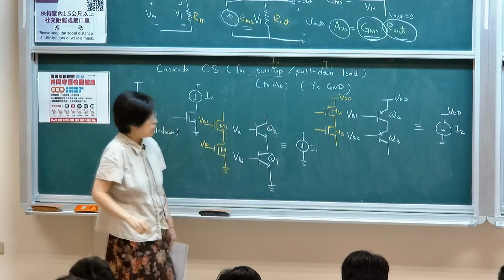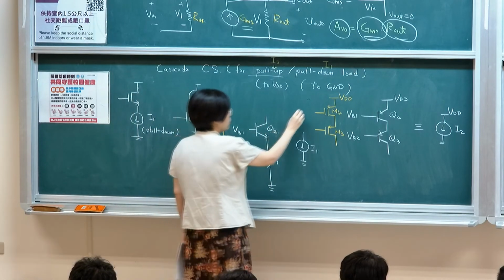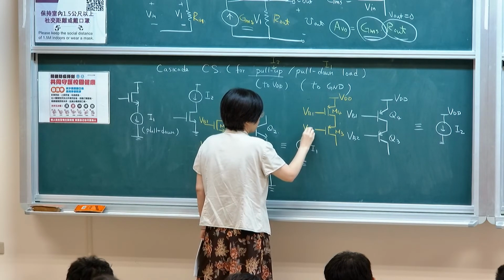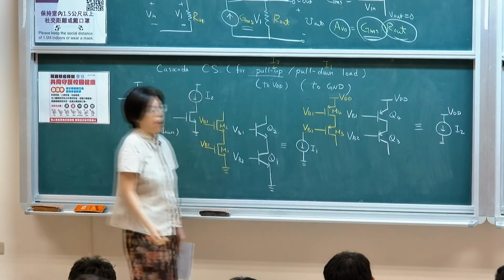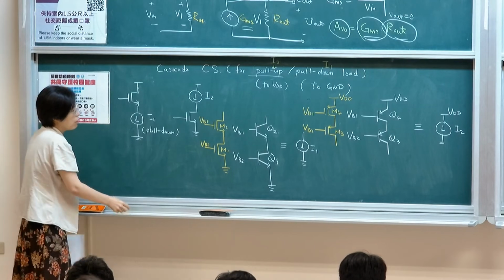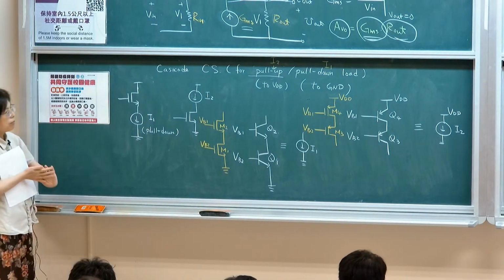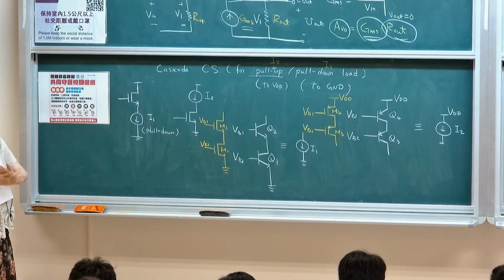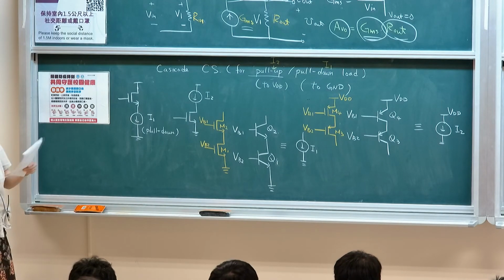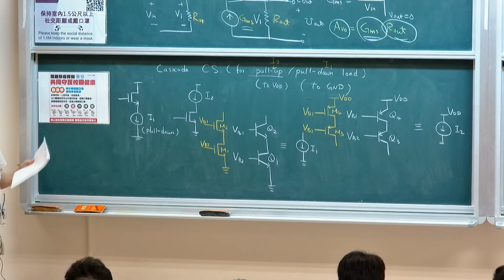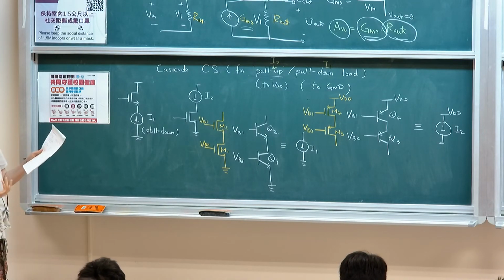To do a current source, you typically want the bias of your gate to be fixed. This simply means that it's a DC bias. All the gates are DC bias. As I said, this type of cascode structure is to enable the increase of output resistance.